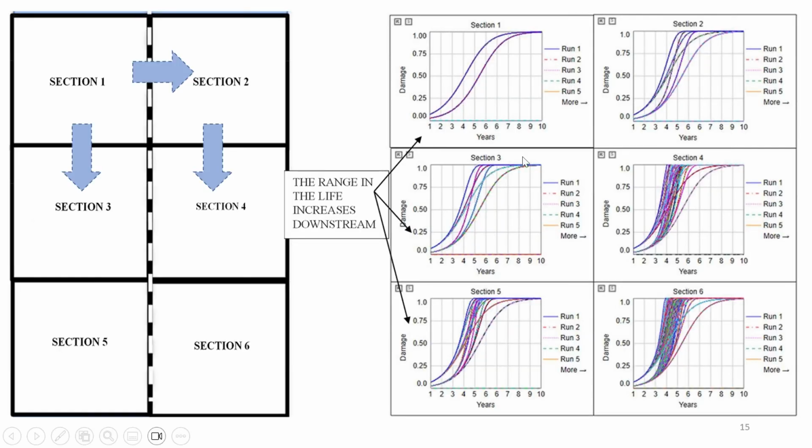So in general, if you take 6 sections instead of 2 sections, and if you have an elevation difference between those sections, and generally you have elevation changes, right? In some parts of the country, you have flat, practically no elevation change, but in most cases, you do have elevation changes. And if you know that the elevation of section 1 is higher than section 2, and it progressively goes down along this, you can actually figure out how the damage progresses in the different sections and which section is the most critical, which will be affected the most.